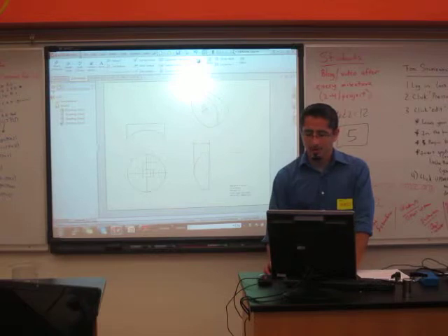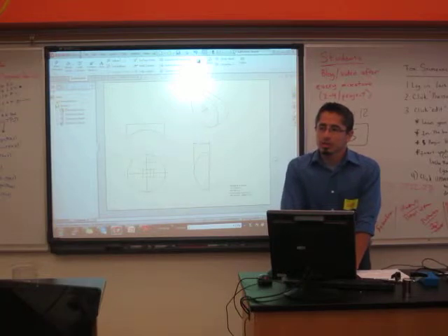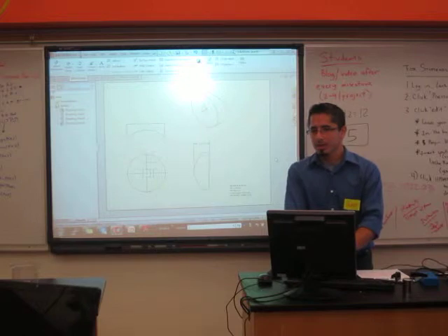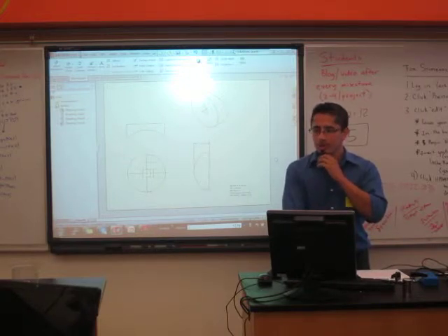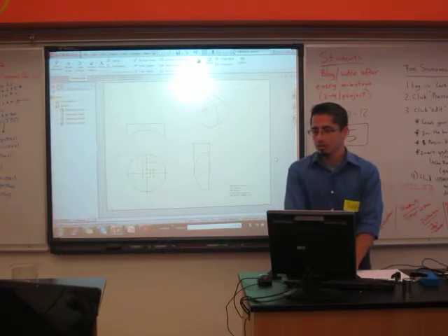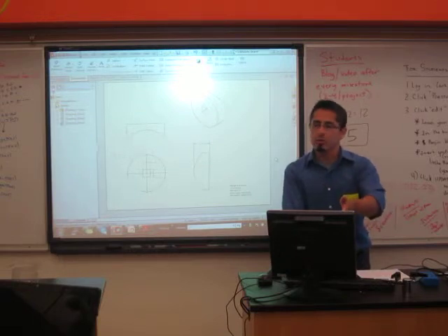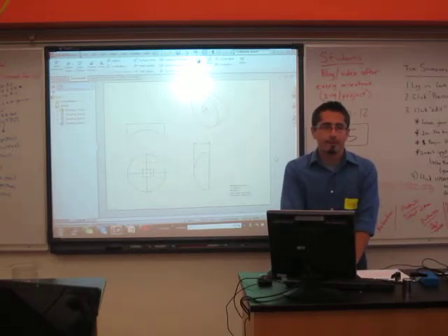If you make a design in there, can you just use that same exact thing that you made and send that to a 3D printer? Usually. So design for 3D printing, this we'll talk next week, is a little different. So this part might 3D print well, might not. But yeah, you can use the same exact model. That's why I like to do it in 3D first, because then I can go right into drawings, blueprints, and 3D print, or send it to a company that does, say, machining, and they can take the 3D file and just machine straight from that. They don't have to redraw off my blueprints.